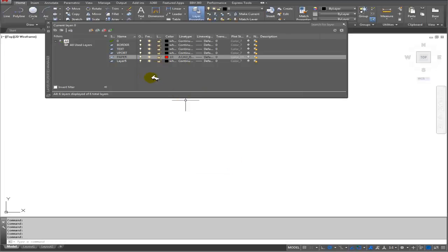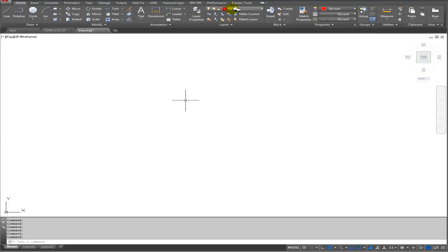So I say okay, that's good. Right now 0 is ticked. It means that's the viewport we are using. Sorry, that's the layer. So I double click on it, and so I activate the paper. So here it says paper. So first I want to draw the paper size. This is just to show you.